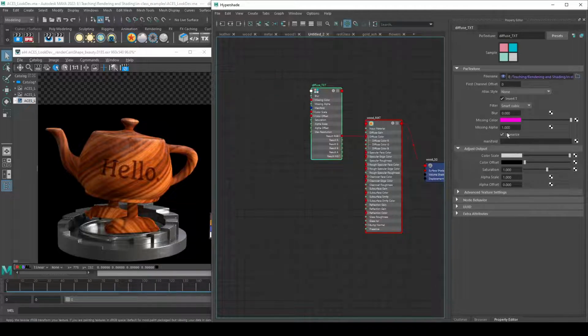And so this only applies to any of our colors that we're going to see in the render. Any black and white data maps like a Specular Roughness Map or Displacement Map, do not click Linearize, because those are just data. That's like raw data. Like, this is my roughness value at this particular surface, and I don't want to color manage it. I don't want to change that value, because when I click on Linearize, it's going to adjust my values.